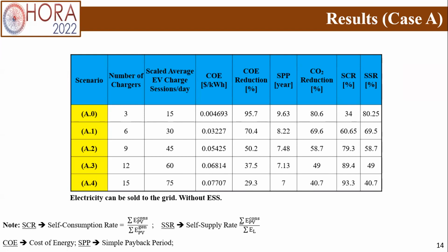In this context, the self-consumption rate, or SCR, which is a measure of how efficiently the PV is used in itself, increased by 60%, while the self-sufficiency rate, SSR, which is a measure of how efficiently the PV is used to meet the demand, decreased by 40%. Due to this decrease in SSR, HBS amortized 2.6 years earlier.